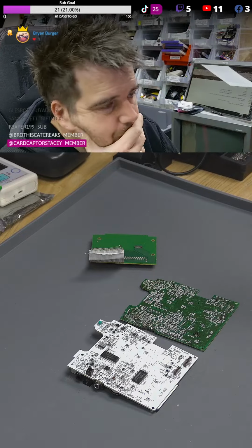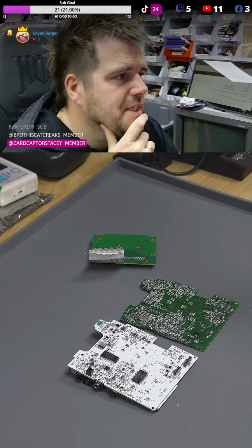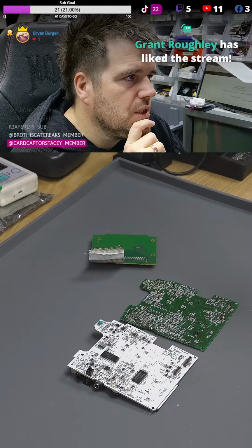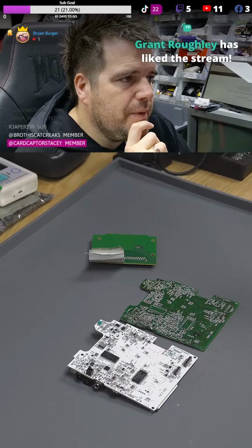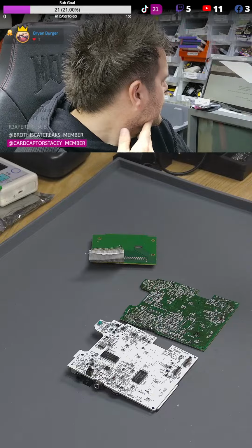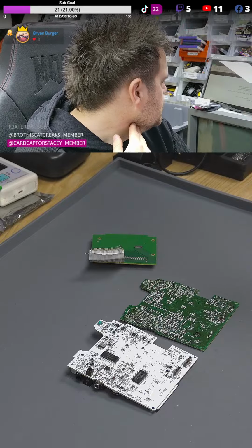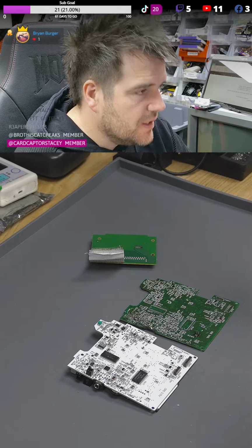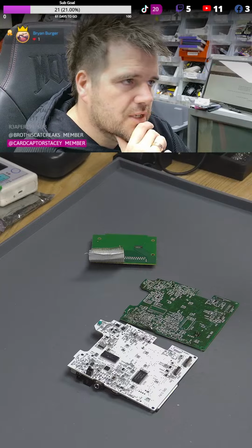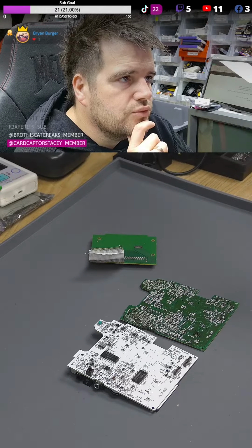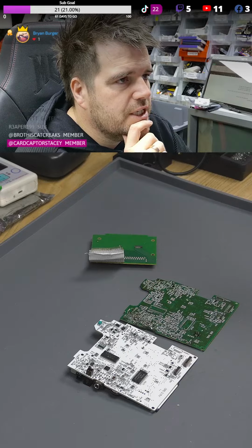So, yeah, there's going to be nothing on the PC Engine schematic. I think it's definitely the power regulation side. 501 was a 6-pin dual. We see the only 5-pin transistor we've got is the epitaxial one we've just identified, so it's not going to be that. Okay, so I think we're now down to a DigiKey search.